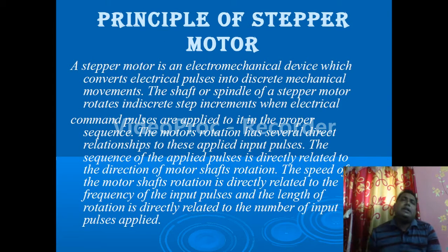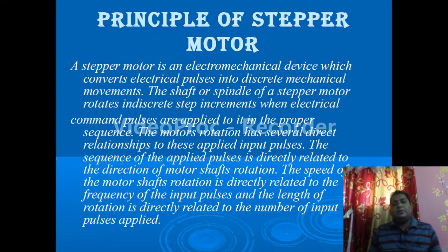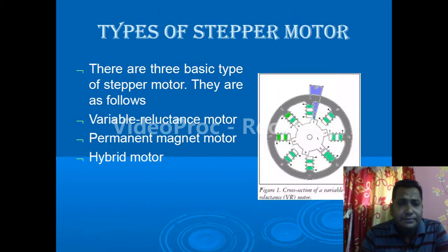So two things we can say over here. How fast the machine is acting will depend upon the frequency of the system, and how far it will rotate, or how many steps it will rotate, depends upon the number of pulses, the number of inputs we are giving to the system. So now coming to the next slide.